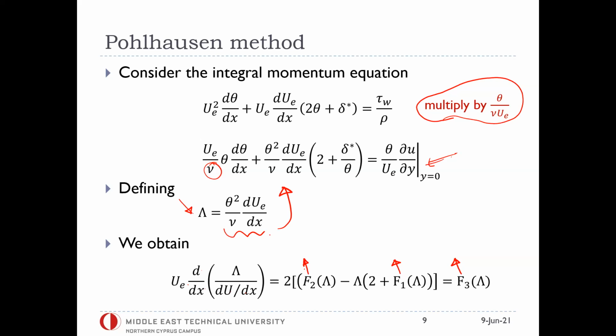Can I ask a question? Yes. Do we treat the Blasius equation as the exact solution for this case? I mean, comparing with the approximations. Yes, for a steady incompressible laminar flat plate boundary layer, yes. Thanks. All the rest that we discussed are approximations. Any other question?